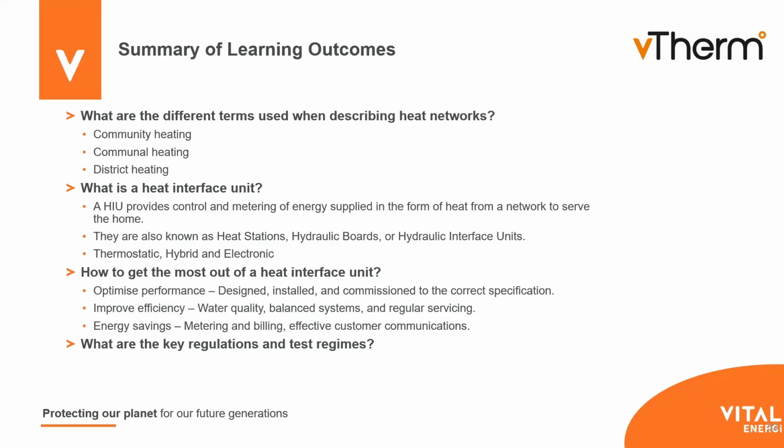How do you see if the wiring's been done correctly? How do you see if you've got a small leak on a HIU if you're doing it remotely? So we always recommend it should be 100% on-site commissioning. Making sure that water quality, making sure the systems are balanced and they're regularly serviced.